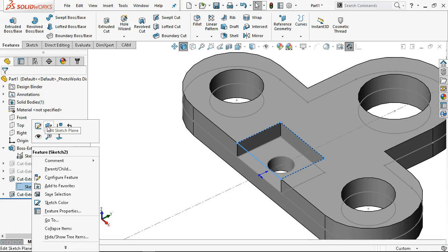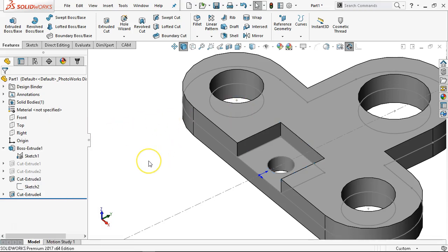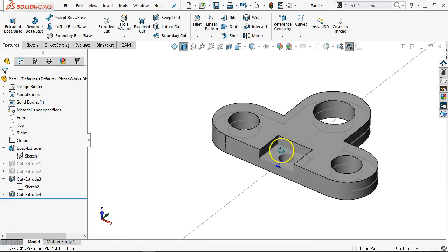And usually it takes me 3, 4, 5 times of, I know I can get this sketch to work, I know it's something in the sketch. At some point, if it clicks that I've lost that face, this is where we come and edit the sketch plane, reselect the face, and that's going to correct the geometry. It's a nasty little trick.